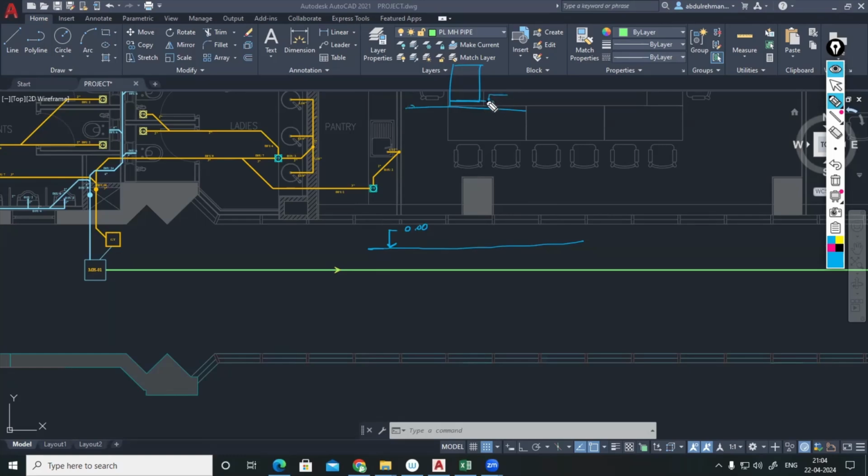Normally, suppose if this is your building and this is the ground level, you might be having the interlock level. On the interlock level only we will be having the manhole cover. So that interlock level we will be marking as 0.0. Anyhow, the reference level after the survey from the civil team only we will be getting, because with respect to the building survey we will be having a survey point. So any point we will be getting for that.